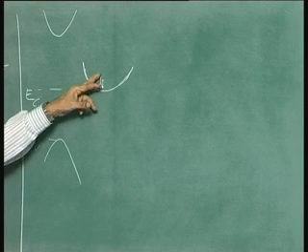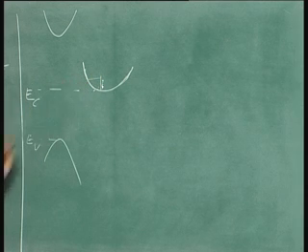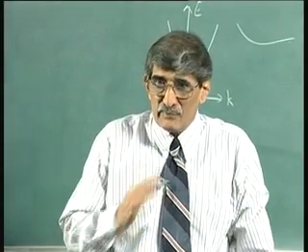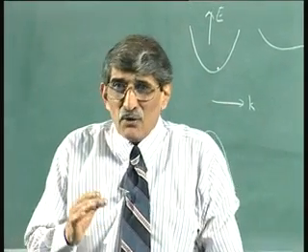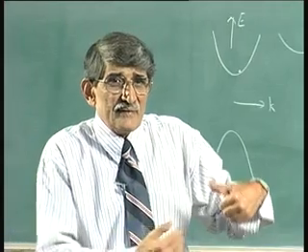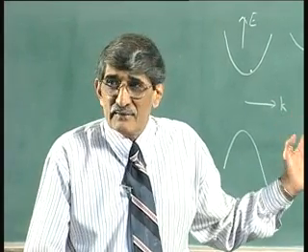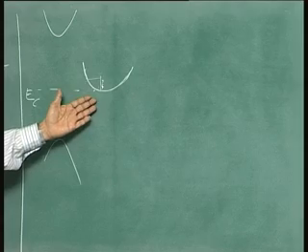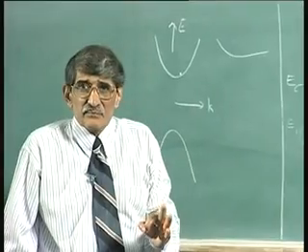It may overshoot, then come back, because of the difference in the relaxation times between energy and momentum. But the momentum difference is not so much as in the case of gallium arsenide, etc. It is only within that curve, the E-K diagram. So, the transient takes place in a very short time.